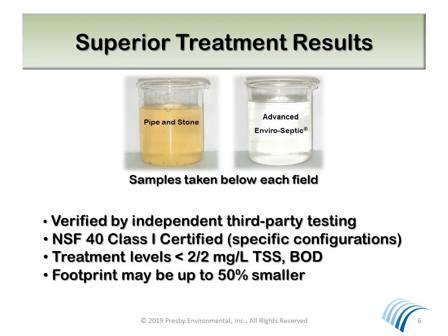An important point for AES is that nearly all of the effluent treatment happens within the AES pipe. The surrounding sands only serve to carry treated wastewater back to the subsoil and provide a polishing effect. This is drastically different than the traditional pipe and stone system, where the soils are actually doing the filtering and treatment, explaining their large footprint.